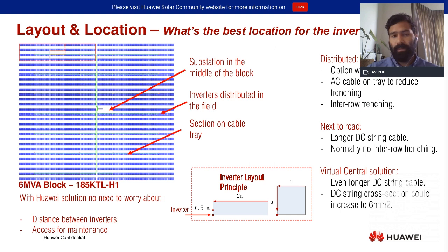In terms of the inverter, there's no difference, of course. The inverter could work in both situations. There is a third solution. Some people call it a virtual central solution or a cluster array, where you put all the string inverters very close to the substation.